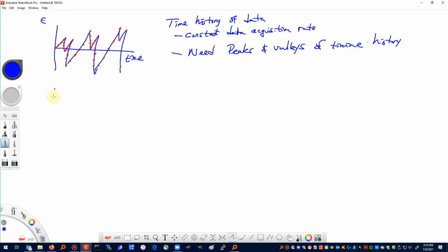All right, so I'll draw another simple waveform. This would be a cosine wave. And often in testing machines, for reasons we'll talk about in class, we do testing with sine waves for fatigue testing. And so again, we may have a whole lot of data points along the sine wave. And there's actually recommendations if you know the frequency. But again, when we're going to talk mainly about metal fatigue, our purposes are mainly interested in the peaks and in the valleys.